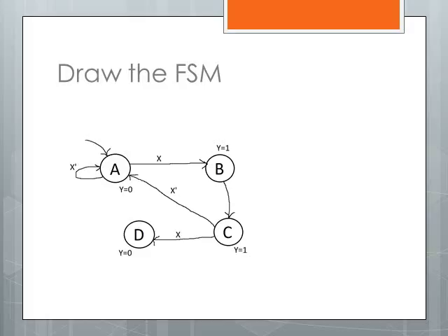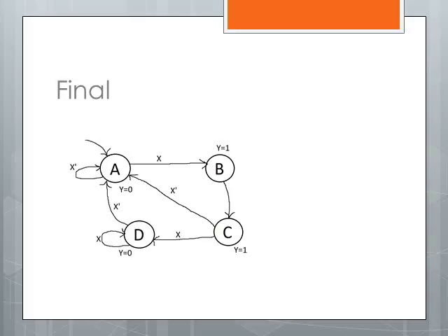So in this case, that means that when x is still 1, you want to stay in that last state to make sure that y stays 0. Otherwise, you'll have the problem like before where you only had the 3 states and it just loops, which we don't want. It is only when x transitions from 0 to 1 that we want y to have that loop of being 1 for 2 clock cycles. So that's where the key part is.